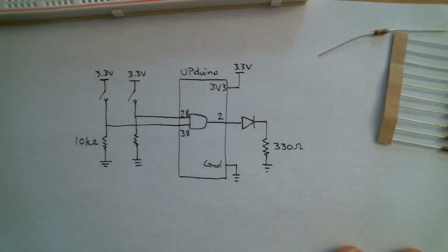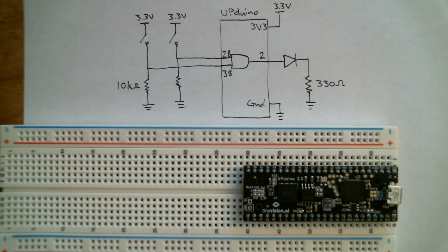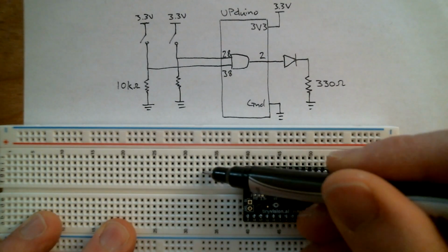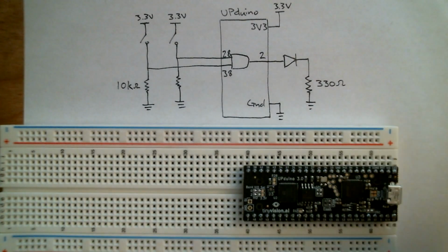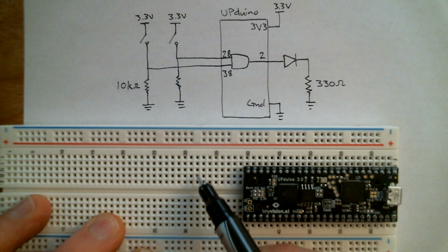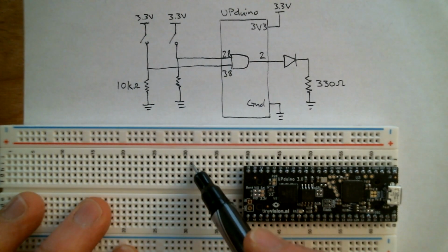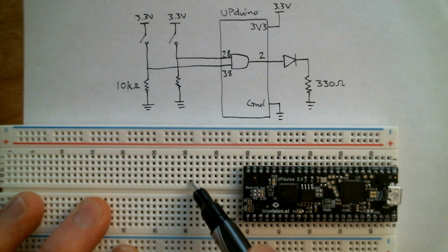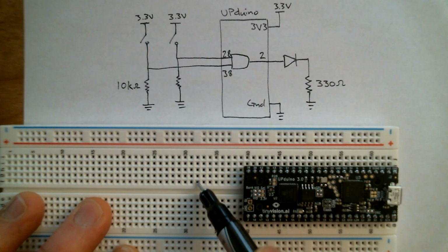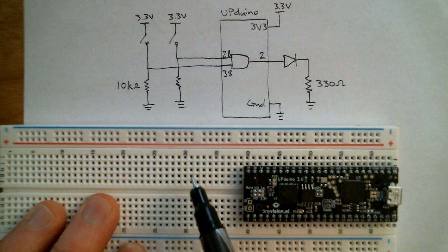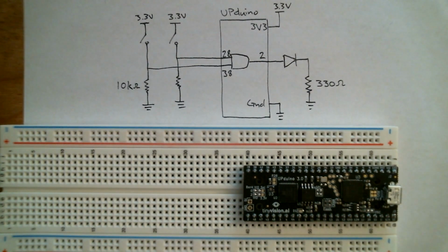Okay, so that's our complete circuit, and now it's time to wire it up. If you haven't used a breadboard before, the important thing to know is that each column of holes here, or each row depending on how you've oriented it, but each column, the way I'm showing it, is electrically connected together. So these 5 holes are all electrically connected together, and they're separate from the next row of holes over here. Anything you connect in the same column will be electrically connected together.